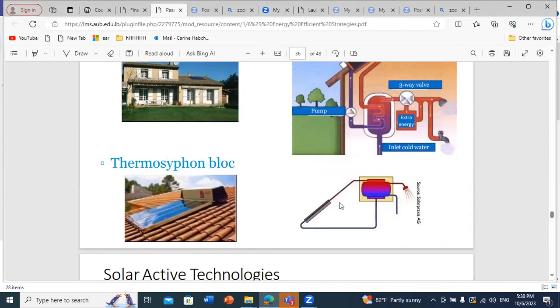And this is why you have a certain inclination allowing the water to circulate within your system. As the water enters the PV array, it will be heated, and due to the heating effect the density will be reduced, and then you have motion by buoyancy effect.